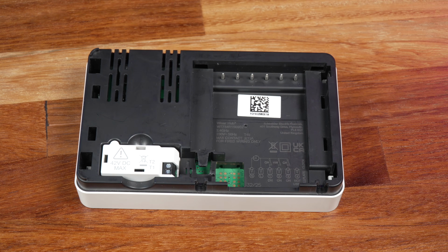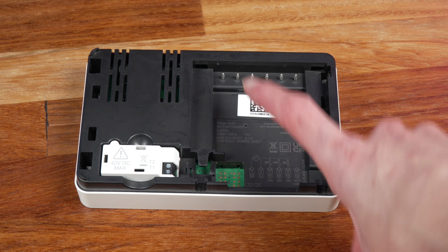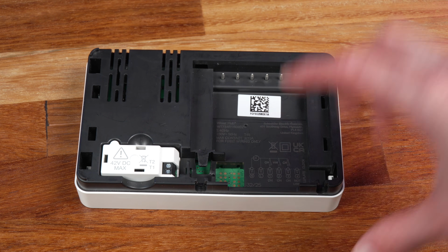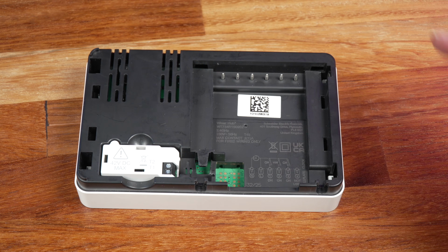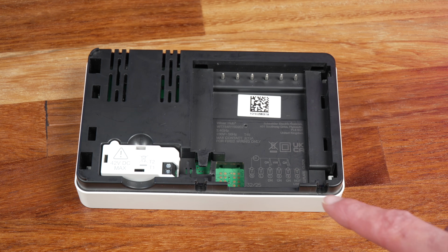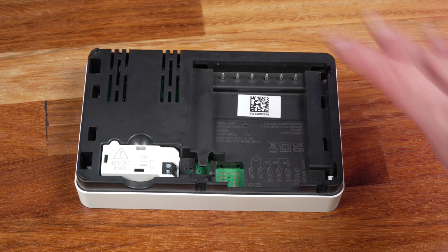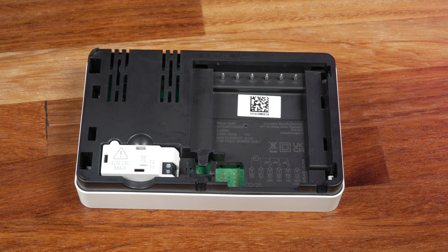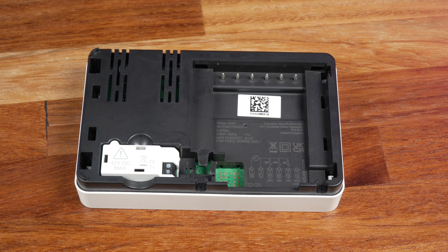Now I'll go into much more detail in that video, but as a very quick summary, it does work with OpenTherm, but only on the first heating channel. The hot water channel and the second heating channel, so your second zone, will not trigger the boiler over OpenTherm. Only channel 1 can trigger the boiler when OpenTherm is being used. However, when you're using OpenTherm, the relays do still operate. So it's sort of usable for my particular dual zone setup, but the boiler will only run when the main zone is calling for heat, so it is a bit of a limitation.